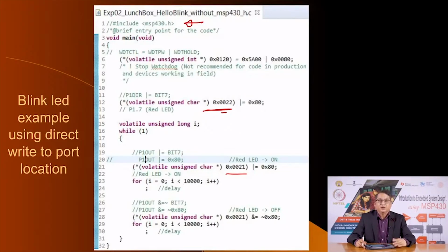So, the whole point of this exercise was to illustrate that when you are compiling code, essentially all these instructions at the end of the day for a von Neumann architecture modify certain memory locations, whether they are registers or variables or constants, they are all in the same memory map. If it was a Harvard architecture, then of course there would be data memory which you would need to deal with in a different way, and you would have program memory and you would need to deal with that in a different way.